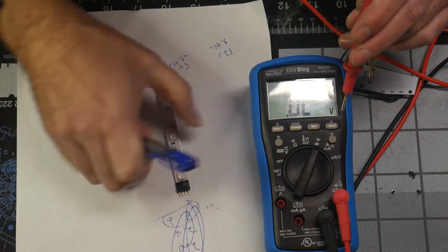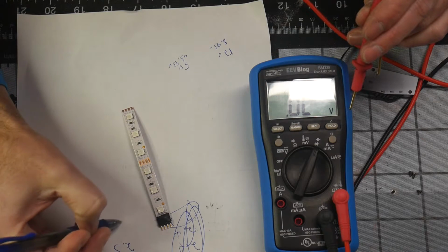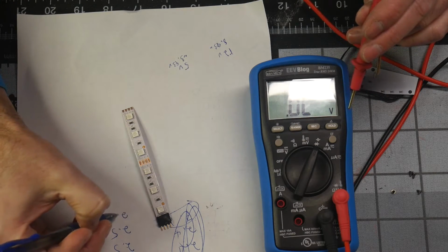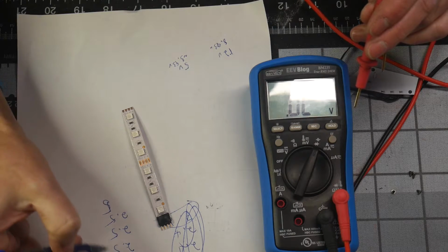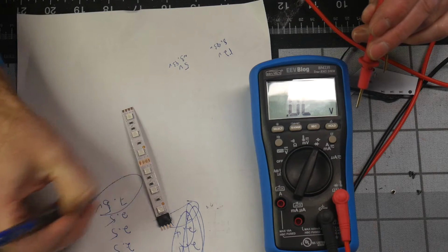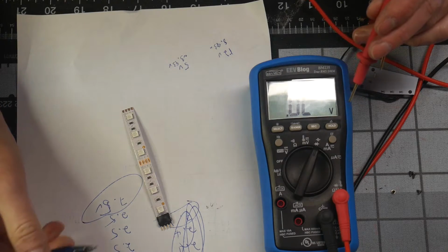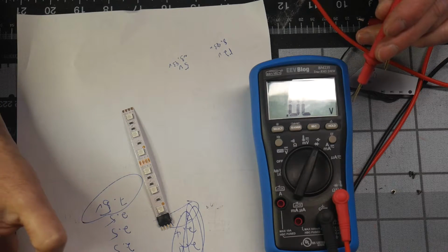We have a 12 volt supply. We know the blue requires 2.5 volts, and because they're wired in series, we combine them, and it goes up to 7.5 volts. That's required to light these LEDs up. Then we use the resistors to limit the current, how much current is produced.